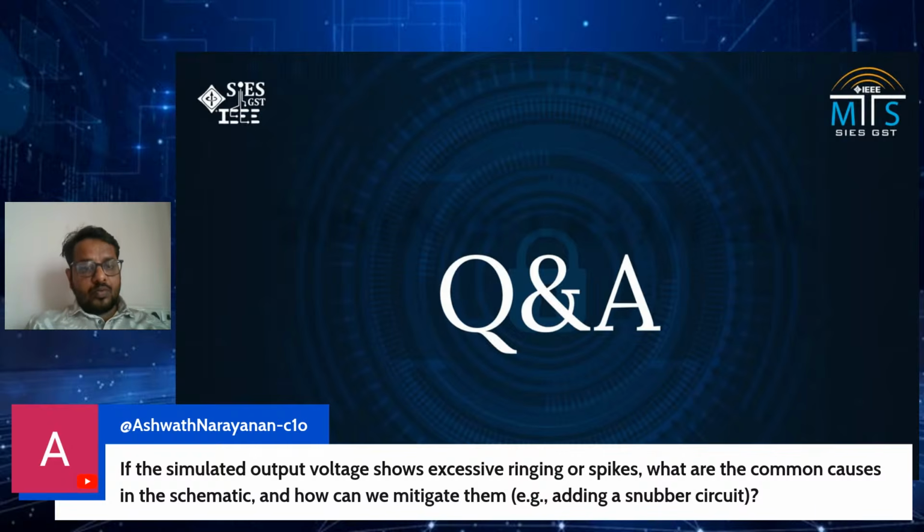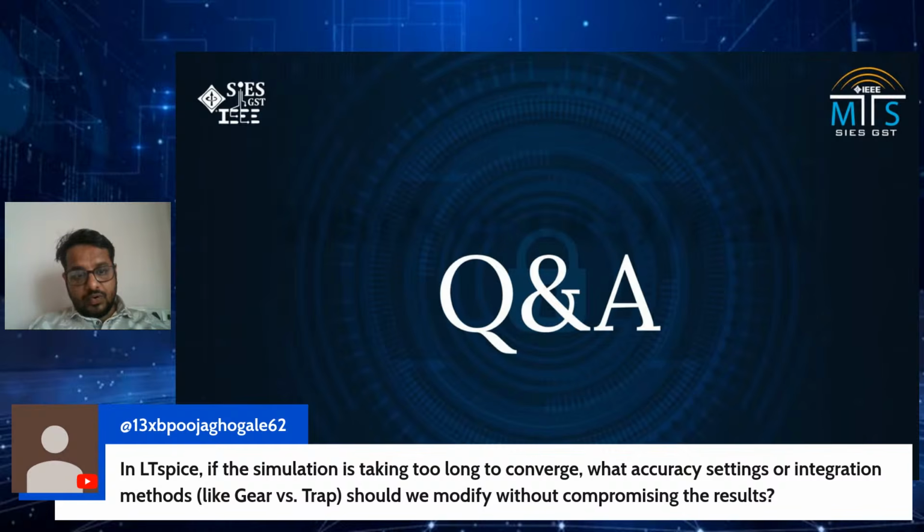Generally, the output voltage will not show much ringing. The ringing will happen across the MOSFET or diodes. So there are snubber circuitries and filter circuitries which we can add, which will help in removing the ringing. Okay, I'll move on to the next question.